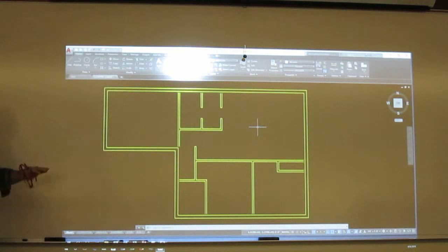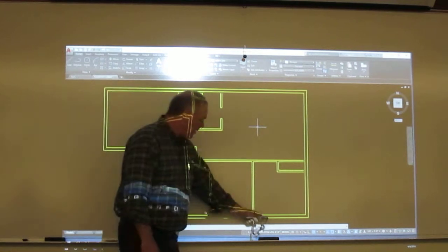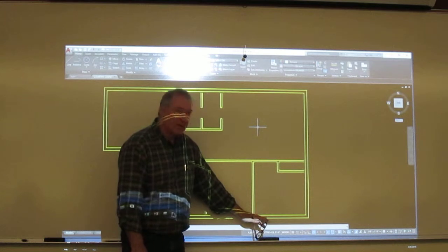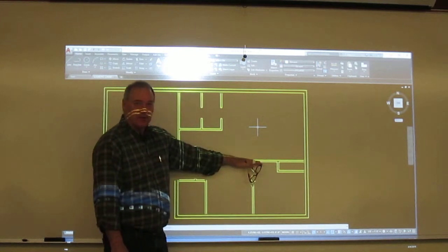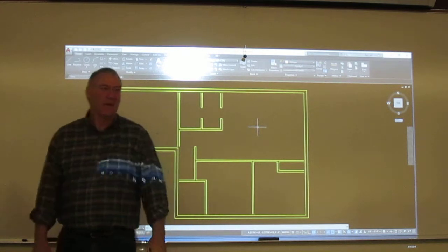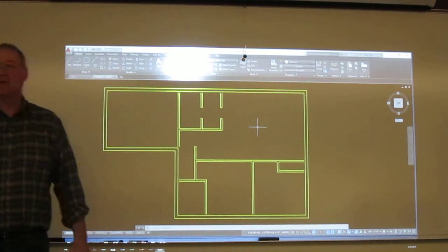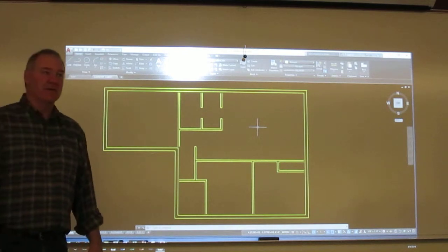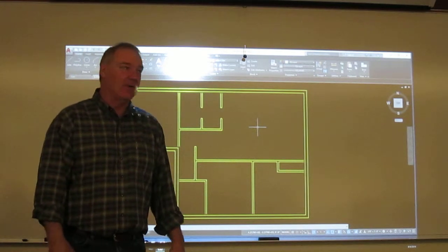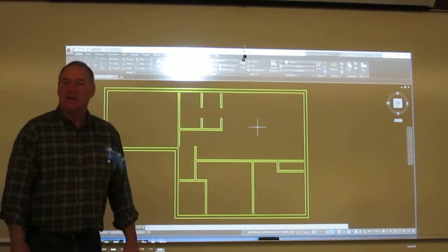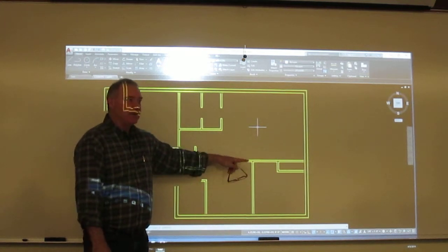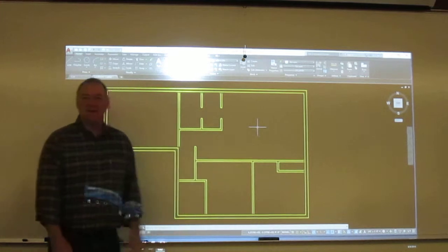Now, you do have the full section that comes through approximately in this location. When you draw the basement, you're going to catch this exterior wall and its footing, this interior wall and its footing, this exterior wall and this footing. But remember what a section is for. It is for the major building components. And it's done at a fairly large scale, like 3/8 to a foot, where we've reduced the item a substantial amount, 32 times, I believe. And you're probably not going to get a good look at this footing in that view. So you probably ought to draw another detail of it.